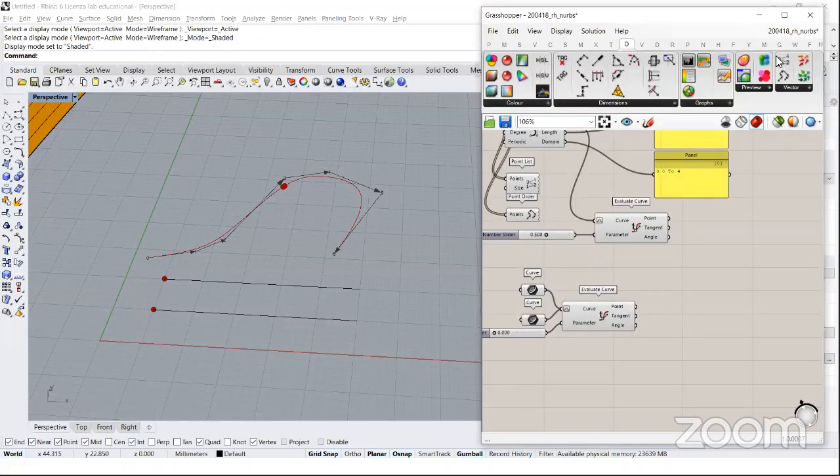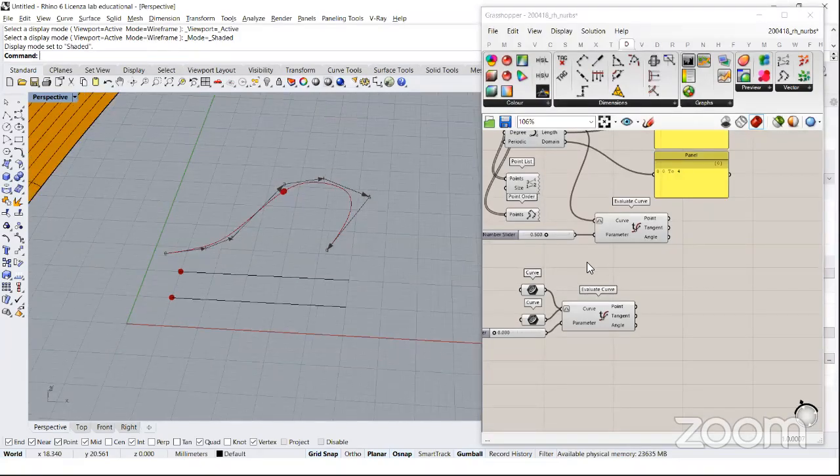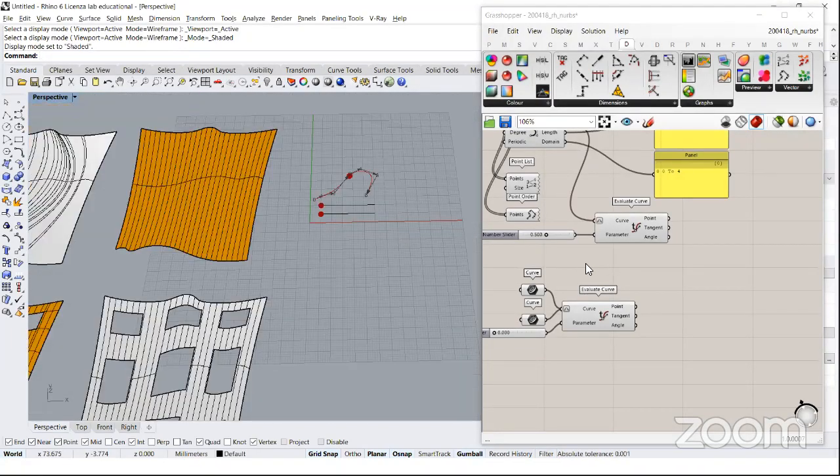Any comments? Yes, of course, because when you import a surface in Grasshopper, the topology is already set in Rhino, so everything depends on the topology of the object that you are importing in Grasshopper. Grasshopper by itself doesn't reorganize the topology of the objects. Okay, so if you have an incorrect topology in Rhino and you import it in Grasshopper, then all the commands that you use on that surface will respond to the actual surface topology, as well as curves.